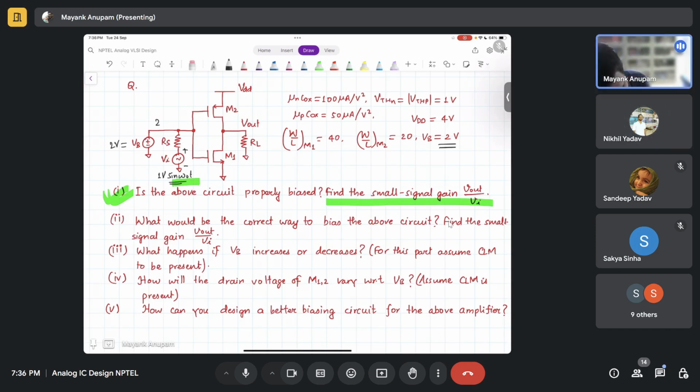So what will happen? Okay, you are saying this. Let's say I reduced RS, and this is the extreme condition for reducing RS, right? I shorted them. So tell me what is going to happen. I think I spoke a lot on this, right? What is this condition? You are trying to short two voltage sources. What is going to happen? Yes, Nikhil. It might go to infinity. The voltage will not go to infinity. The current inside these voltage sources will suddenly increase, right? It's not a good thing at all. You should not do that. So what should I do?